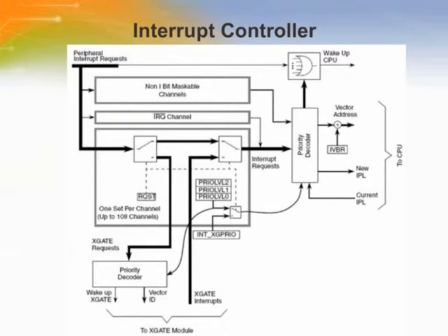New interrupt vectors include one for detection of spurious interrupts, like where an interrupt source is removed before the vector is fetched, one for the new SYS instruction, one for CPU MPU violations, and one for XGATE microprocessor unit violations or software errors.